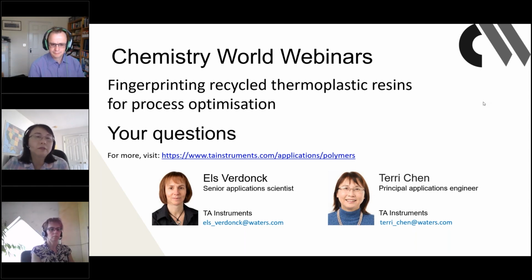Because of the time limitation, in this talk on the rheology section, I only focused on melt rheology processing and did not get any chance to talk about the end product mechanical strengths. If the recycled polymer is a mix of immiscible polymers, the final end product property will be significantly affected.